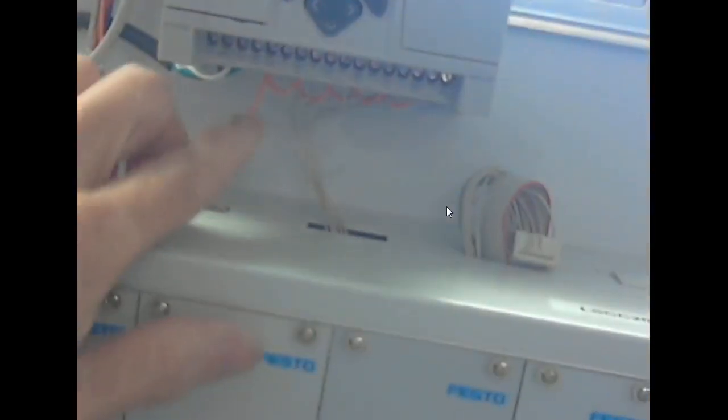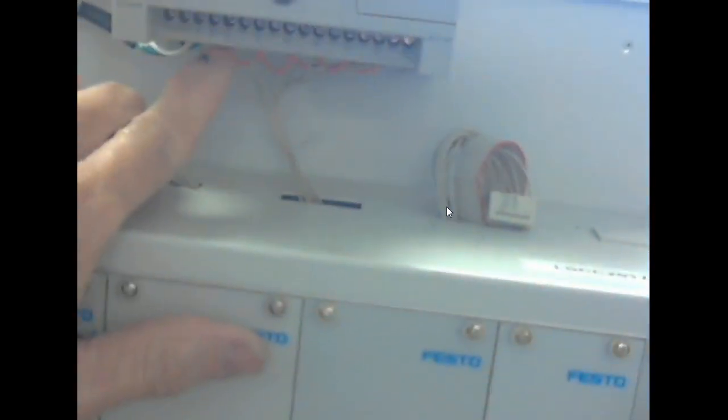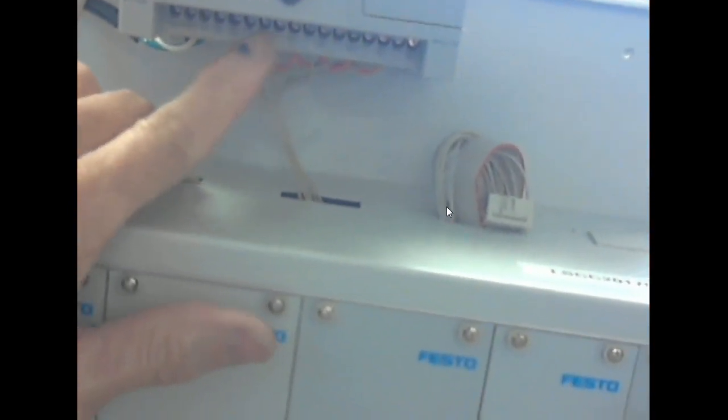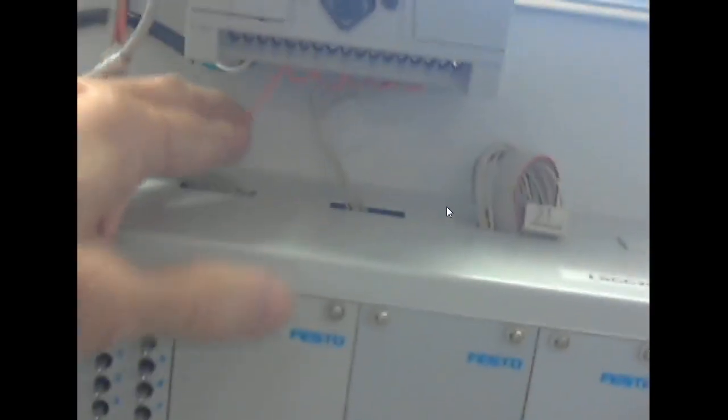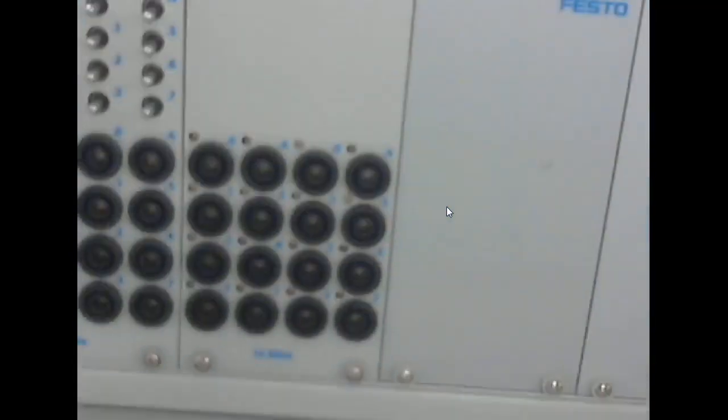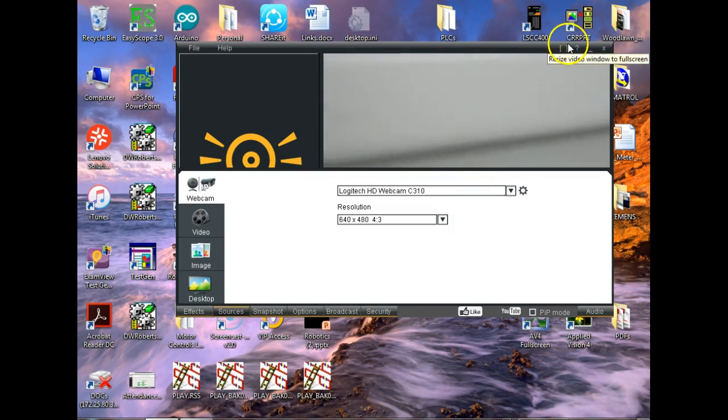I still can't get this to focus in, but that says common. It says AC/DC, AC/DC, AC/DC. So this is the plus coming up. What I'm doing is I've got my outputs hooked up as sourcing, so all my ports down here are going to be set up to sink, right? You understand that? Will that help you, Gary?